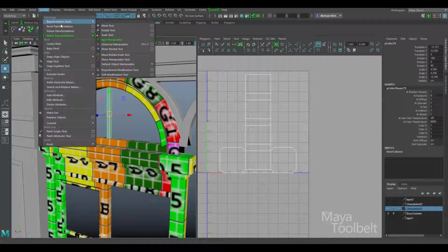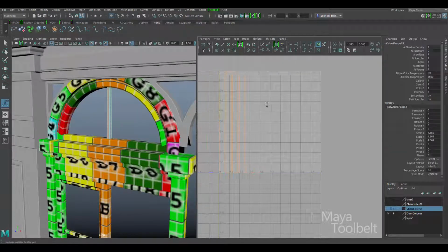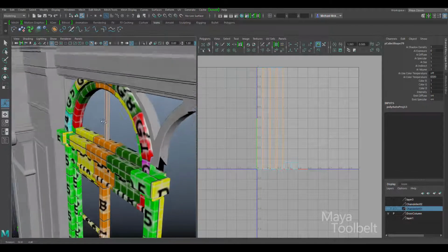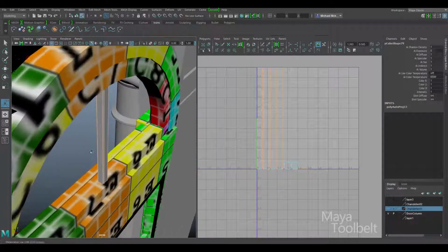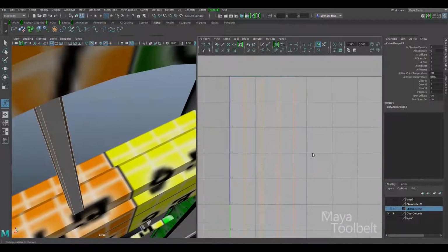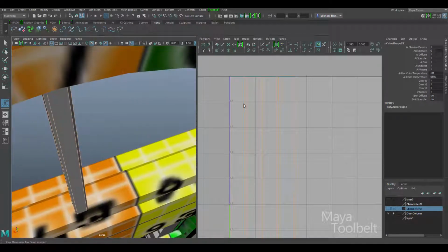Okay, got this piece here we could do the same concept with. First I'm going to go to Modify, Freeze Transformations, then UV Automatic Unwrap to just give us our starting point. Since this is a simpler rectangular shape, I can select all those edges through the middle like this, and then choose an edge to be my seam. Now because this one has beveled edges, I need to make sure I don't select one of the inner beveled edges that are still attached to its representative face.